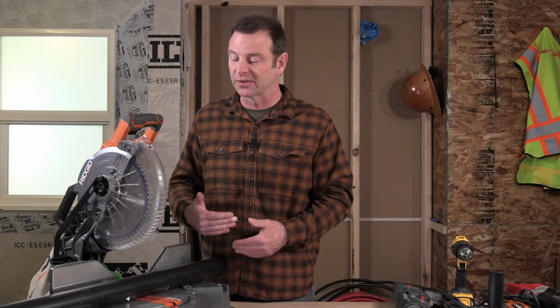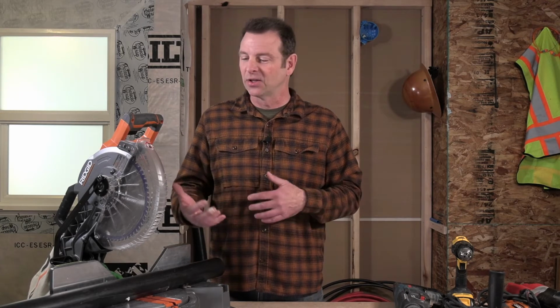A lot of these larger drain pipes are plastic. They cut very easily, and we can make these cuts nice and square and true and very accurate. And this tool can do it quickly. It's a very productive tool. You might not see this tool on a job site because a lot of our installations don't allow us to set this tool up. We don't have time, or we don't have the space to set it up. You might be under a building or in a crawl space or in a situation where you just don't have room to set this up. But if you can set it up or pre-cut some of your parts, this tool will do a great job of that.